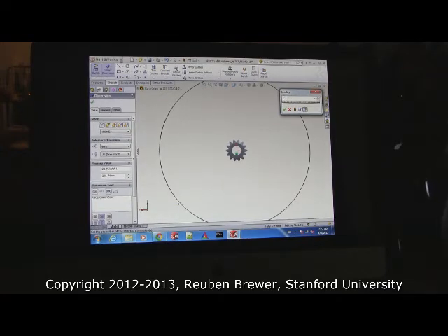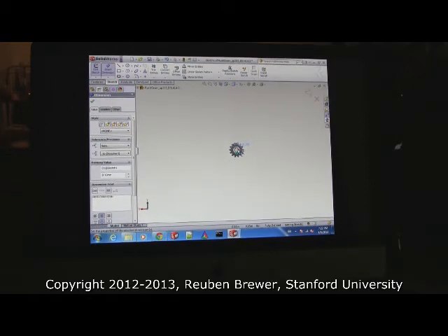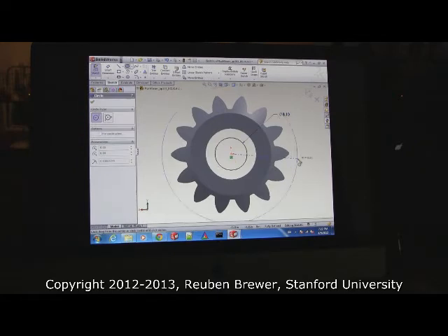I'm going to do 8 is my nominal diameter, and then I want to do a 0.1 offset, and then I want to divide the whole thing by 25.4. Boom! You can do equations in here. Just don't use variables because that'll get you in trouble. Everyone's circle should shrink now, showing that we're back in metric.